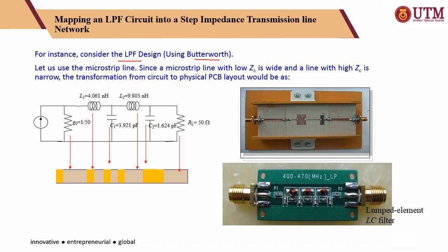Then you determine the normalized elements or components in your filter circuit, and then get the design into your simulator. Perform the simulation to check whether the filter performance is as required or not. And if everything is okay, then you may fabricate that before the final production.